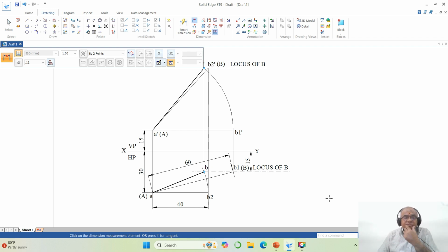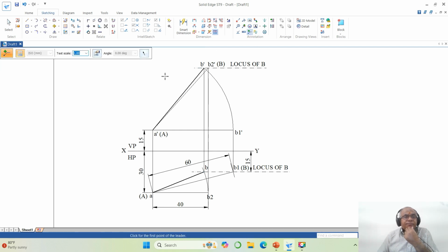So once you get this, now I need to do the directions of projections. So to do that, I'll go to leader. So here I'll take point or element and remove endpoint and intersection. So what I'm doing now, I will project this line first. Then I will project this here. Then I will project this here. This is for the first case.